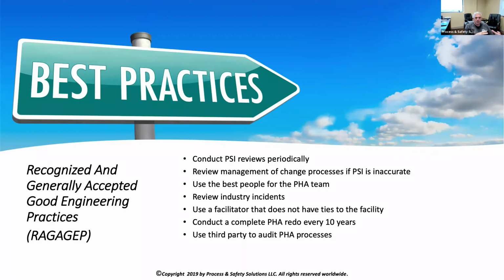So we usually like to see facilitators who are removed from the process, have really no financial responsibilities, and have no direct responsibilities with the process itself. We also recommend, from a best practice standpoint, that you conduct a complete PHA redo every 10 years. And what that means is essentially the PSM standard does allow you to conduct a reval. And a reval is essentially going back to the initial PHA and just revalidating that nothing has changed. And you can continue to do that throughout the life of the process.